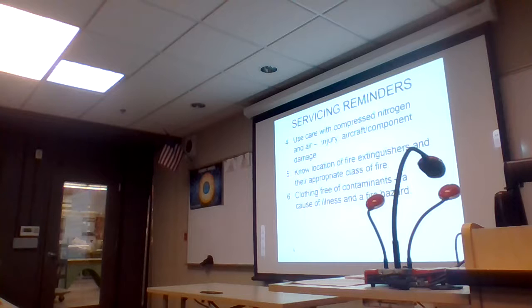Wash your hands after you handle any of these materials. You should be wearing gloves and safety glasses anyway. So with fluids especially, you don't want to come in contact directly with them. Same thing is true with a lot of other things. Turbine engine fuel, I don't like to put my hands in a fuel sump, especially near the bottom. Sometimes there's entrained water, or water at the bottom of the fuel cell, and there's no tetraethyl lead in turbine fuel, and that means there's potential for a lot of microbial growth. So you can end up with a nasty infection by exposure to the stuff at the bottom of a fuel cell. So again, be really careful with this stuff.